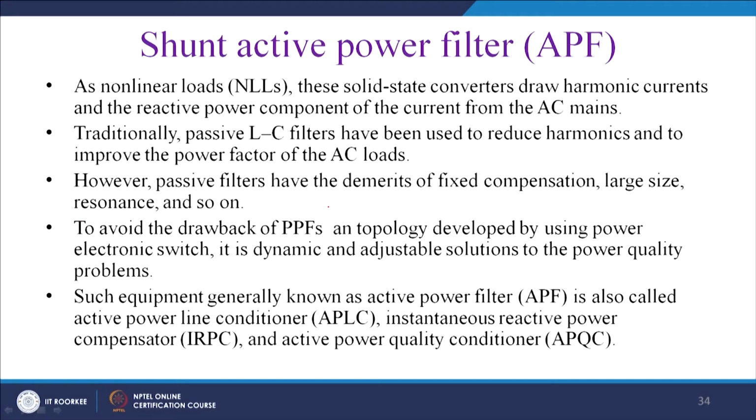To avoid the drawbacks of these passive filters, a topology is developed using power electronic switches, and it is a dynamic and adjustable solution to the power quality problem. It can inject the harmonics as per the requirement.